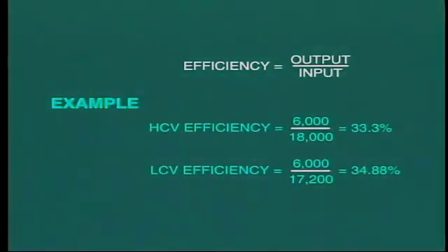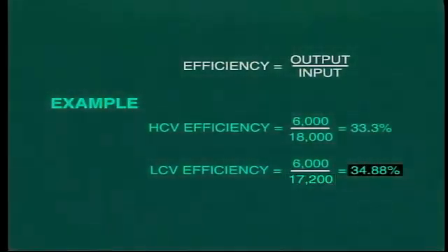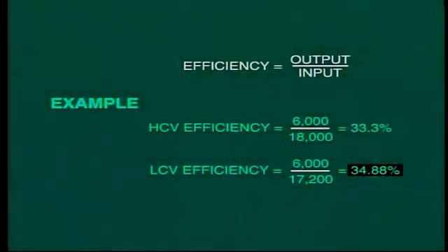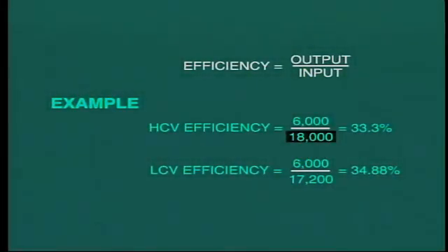However, beware, in many other situations, for example, in many European plants and European manufactured equipment, the quoted efficiency is based on the lower calorific value. This would, of course, provide an apparent higher number for efficiency. Clearly, if the heat input to the plant is indicated at a higher value, then the calculated efficiency would come to a lower number.